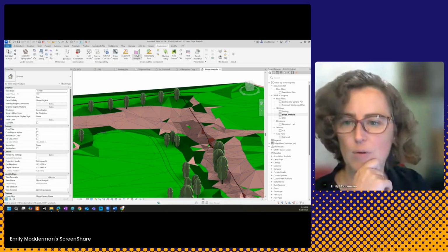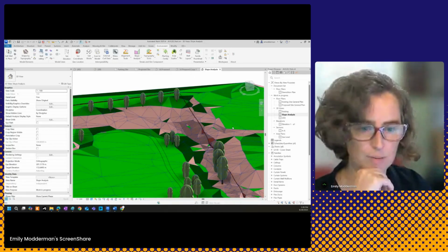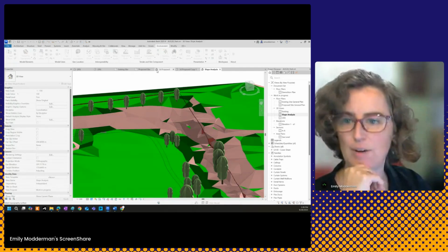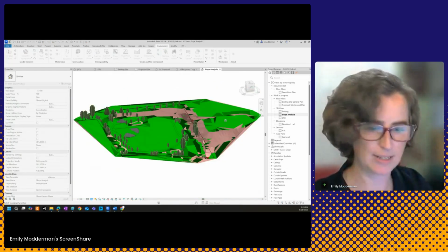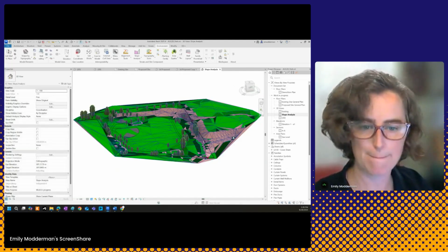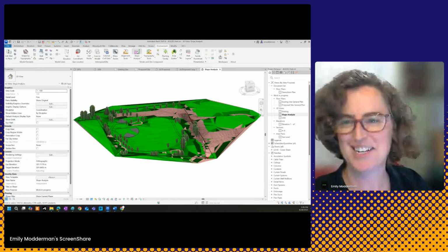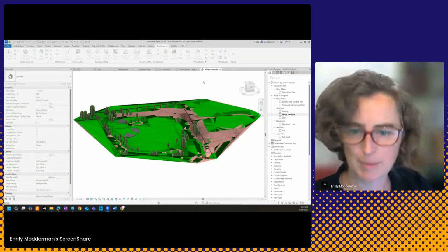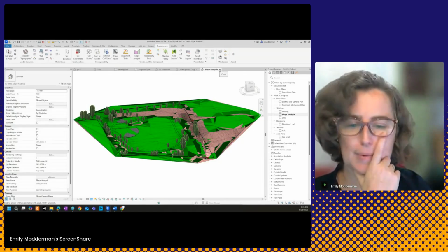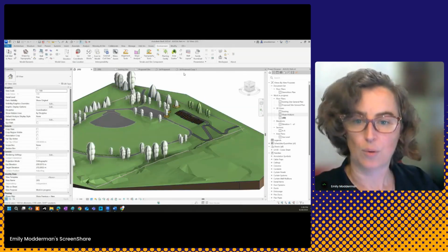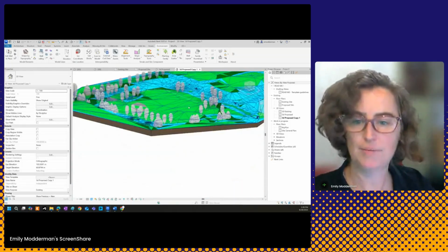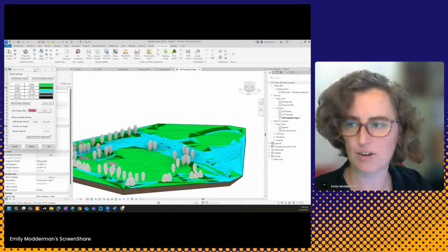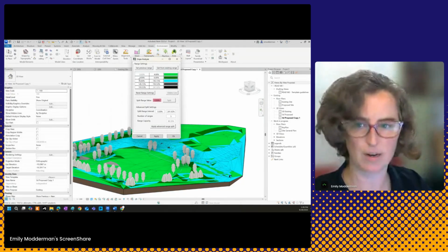And so you can always check out what your slope analysis schedule is by going back to the slope analysis tool, grabbing your site. And I don't know why it's not letting me pick it, but that's okay. It's still there. So I can go back to slope analysis and usually pick that site. Love live demos. So I was able to do that here. And so if I go back to slope analysis, I can select that anytime and just rebuild that range, and it'll bring me right back to what I was working on, and I can continue that work.